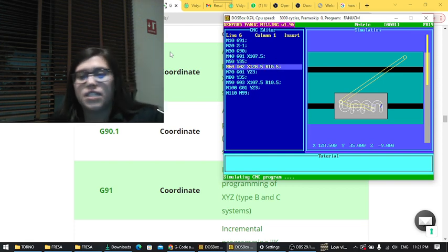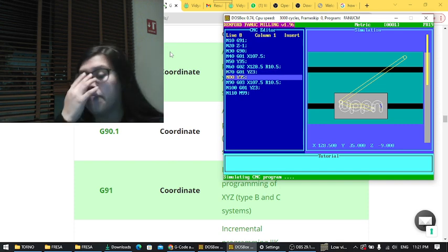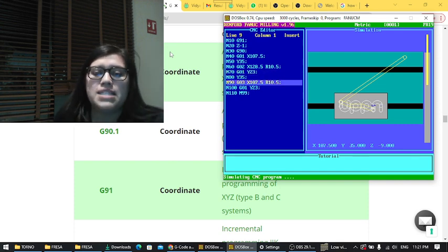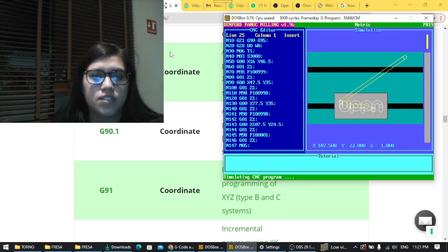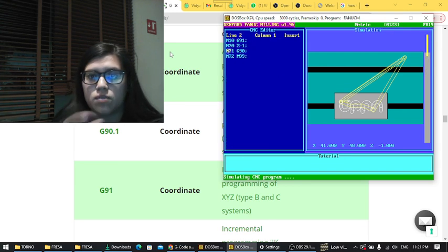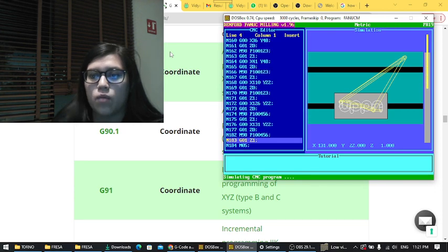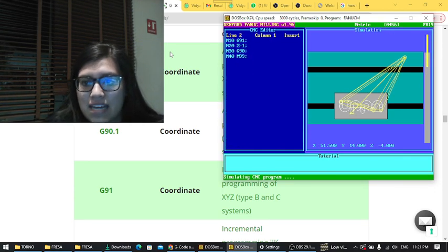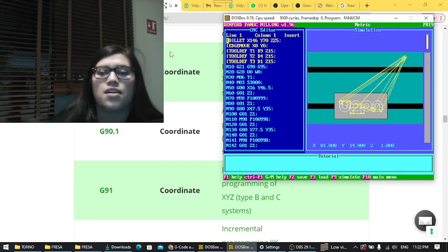Pay a lot of attention to the next process, because it's going to be a flash through your eyes. I actually have another subprogram, but basically it's something really simple. I'm just establishing the coordinates of G90, and there you go. That's really quickly the process. We can see the subprograms right there, establishing that what I want to contour is making each rounded piece into a squared one. And there you go, it's finished.